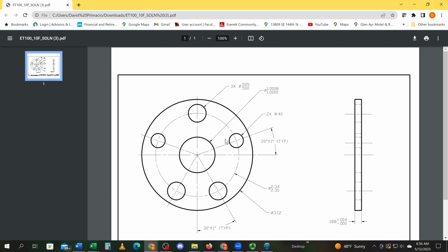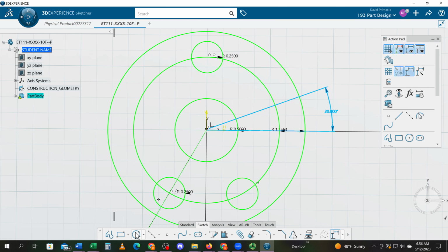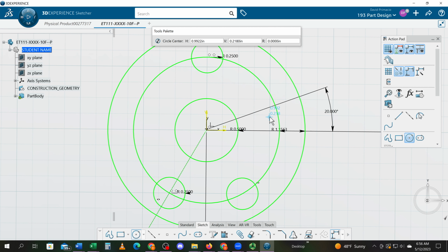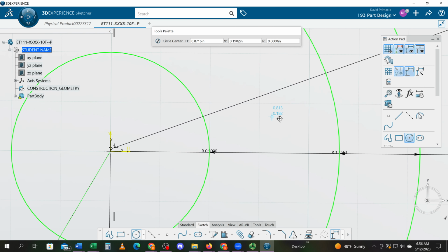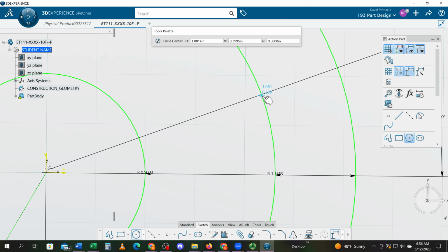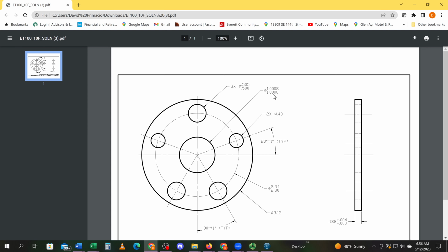And now I want to create that circle. That is 0.40. Okay, so I'm going to use that same center point. We'll go right to circle. Zoom in close. Oh no. I got the extension line for the angle kind of in the way. We'll see if we can get that. So make sure I'm trying to get the axis and the circle highlighted to click on that. And then the radius for this one is 0.4. I'm getting that from here, 0.4.